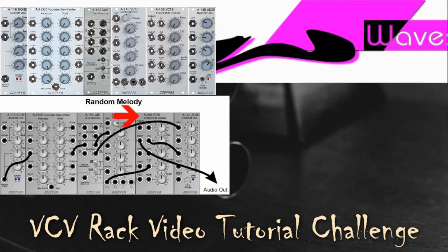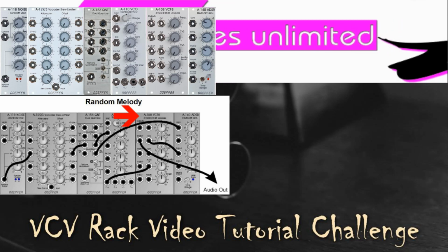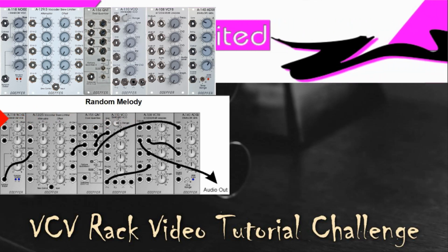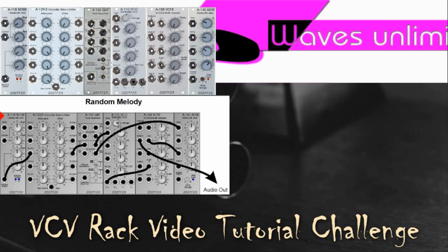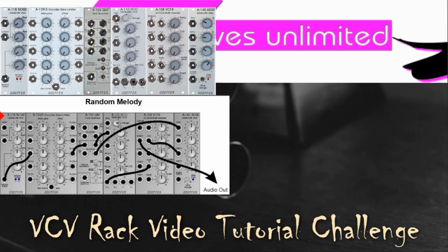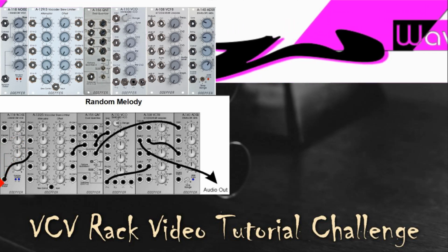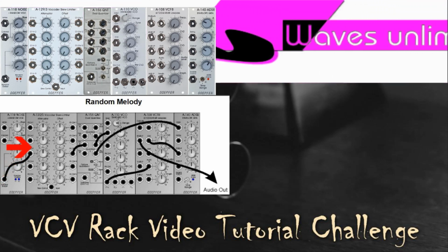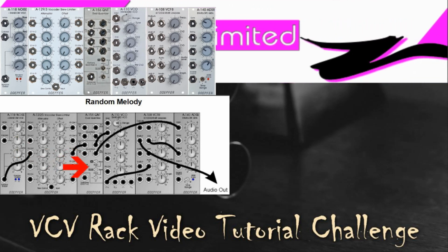The quantized random control voltage for the VCO is generated by the A-118 random output that is processed by one of the A-129/3 attenuator offset generator and the lower section of the A-156 quantizer.